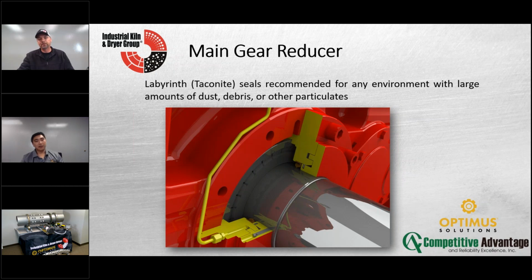I was going to mention, you do have seals that you need to make sure are well designed or well maintained. Maintaining, for sure. A lot of times seals get overlooked. Absolutely. I mean, how many times have you seen, even just on a bearing, oil just coming out? Exactly. It's everywhere coming out of the seals. And what you don't realize, again, a lot of times with a seal, with the heat expansion and contraction, if you've got materials coming out of the seal, and then you've got a dusty environment and it's clinging to the lubrication, this thing heats back up, it's swelling back up, and you're pulling that right back into the unit.